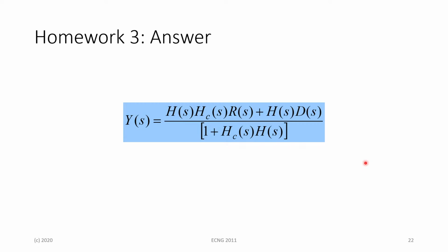And in doing the general strategy, which employs these 4 techniques, you keep on eliminating each one of the summation junctions, and slowly but surely you get down to one final block that represents the entire system transfer function from the output y of s to the input x of s accordingly. If there are any further questions regarding the contents of this lecture, please ask them now.